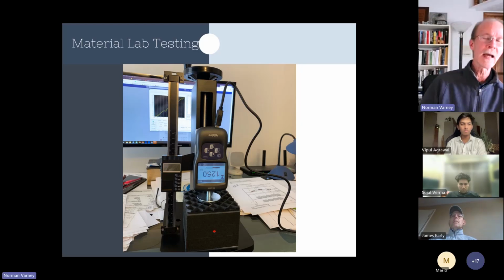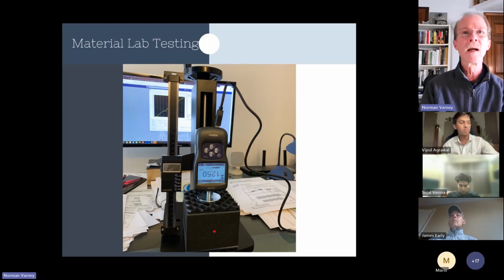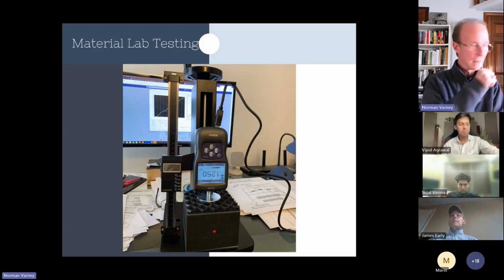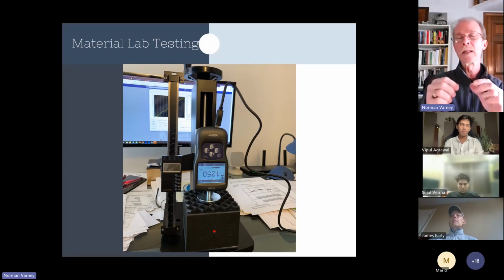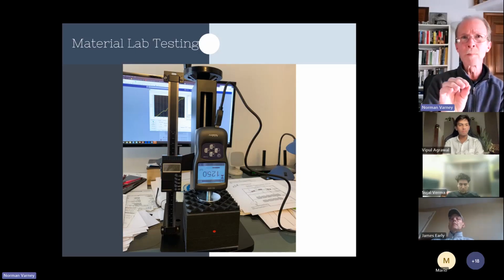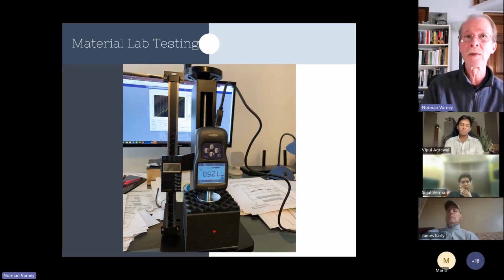When you have a speaker, a sound source coupled to the structure, in other words, your monitor or your subwoofer or whatever is sitting on the floor, and I don't care what it's made out of, it excites it and it causes vibration. In the little video that I do in there, I use just a little music box mechanism. Now that has tiny tines. They're moving plus or minus 0.1 millimeter. It's hardly any energy, not even like from a mid-range driver, more like a tweeter. So it's like nothing, but the tines do go down to 500 hertz.